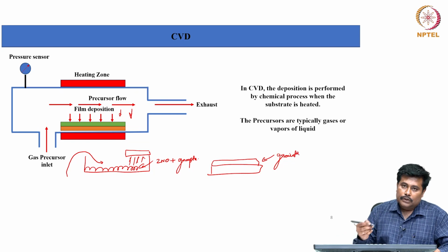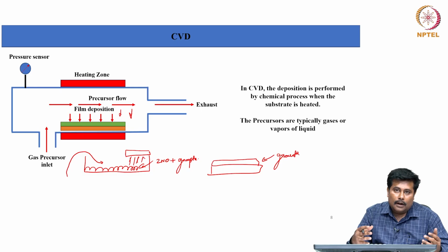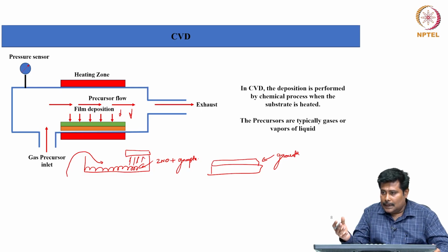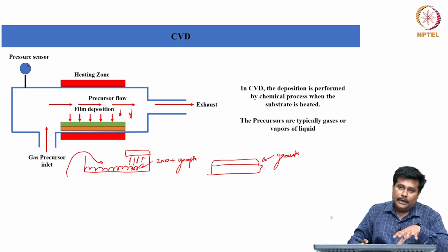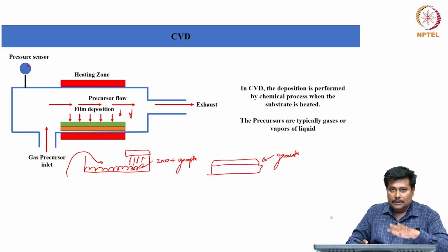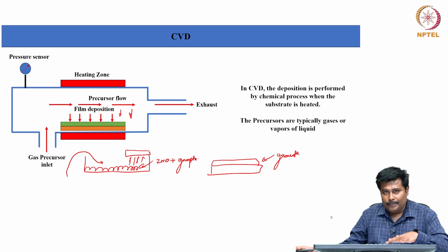of the film. Wherever we are working on high temperature materials such as silicon carbide, this kind of CVD process can be efficiently used. However, one of the major limitations of the CVD process is masking, because masking in a CVD process is quite difficult.